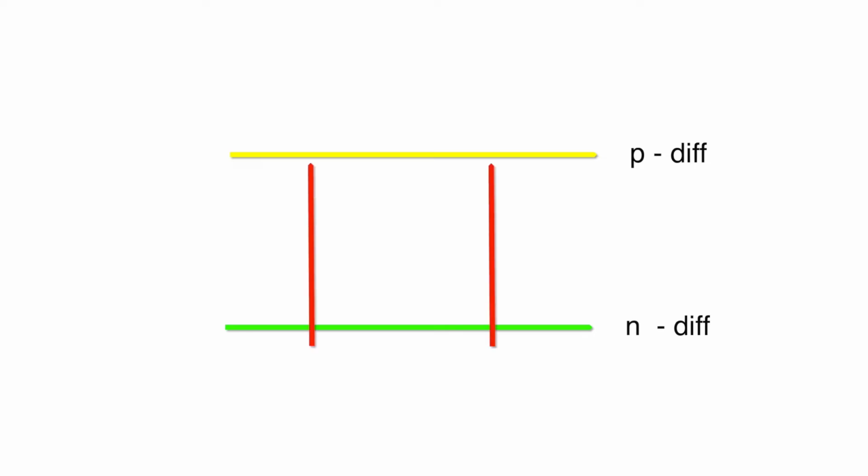C. Trace the number of input red lines, 2 in this example, vertically across each yellow and green line. This represents the gate contacts to the devices that are made of poly. Label each poly line as A and B in order from left to right.